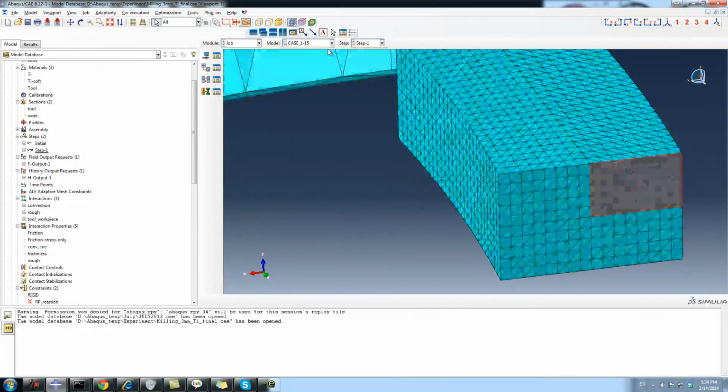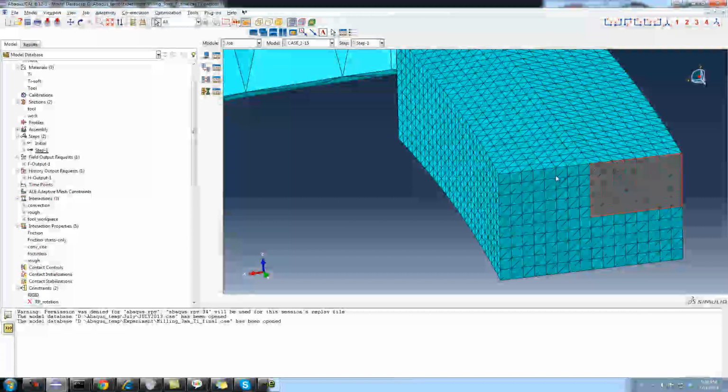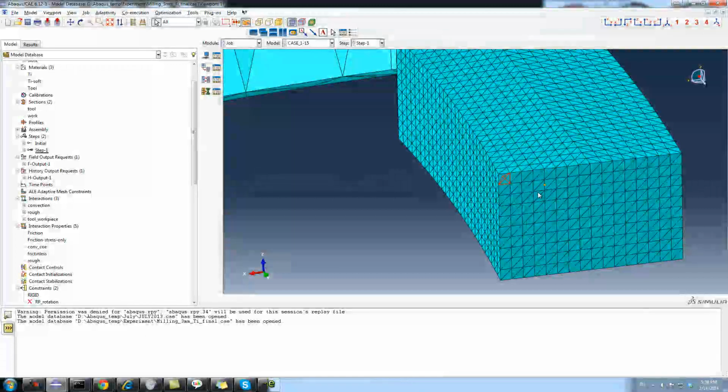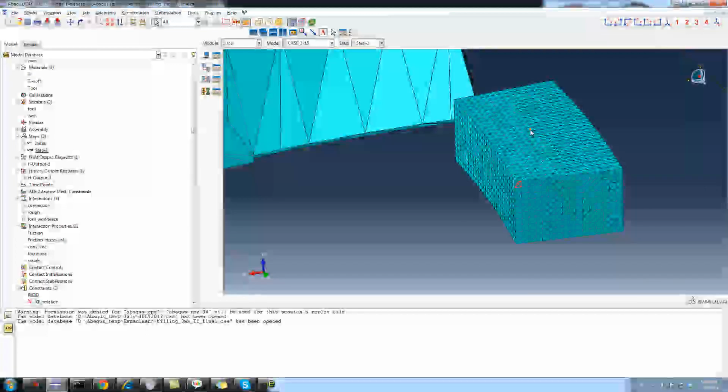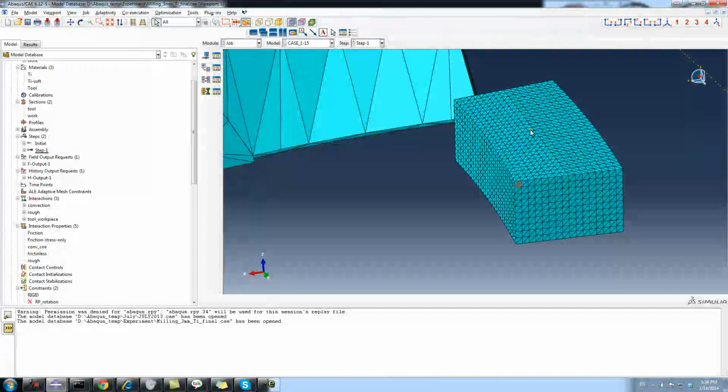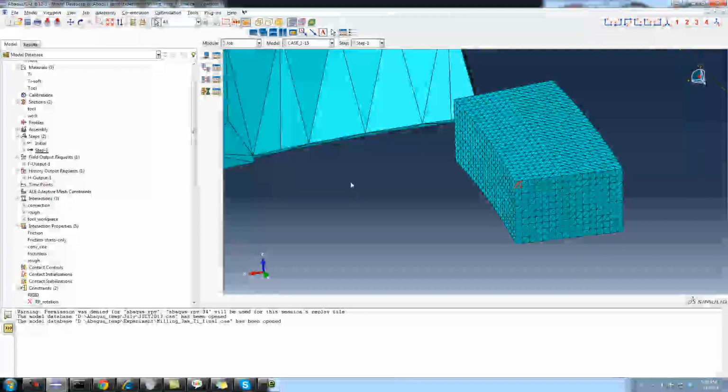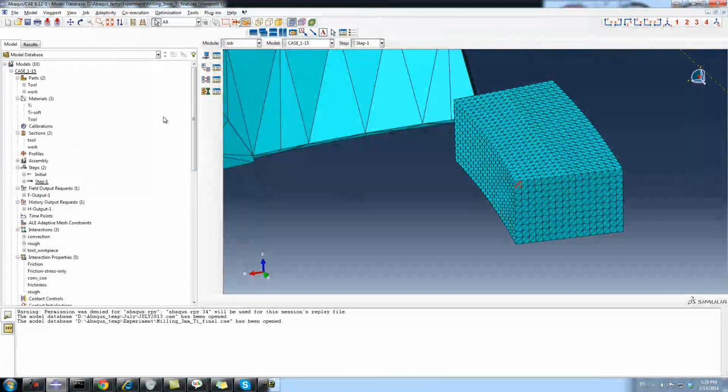This may be for high-speed simulation. So if I open the link files, maybe this part is the fine mesh. No. Initially, I do not use fine mesh. Once the simulation runs successfully, you can change it to fine mesh. Otherwise, it will take a long time.